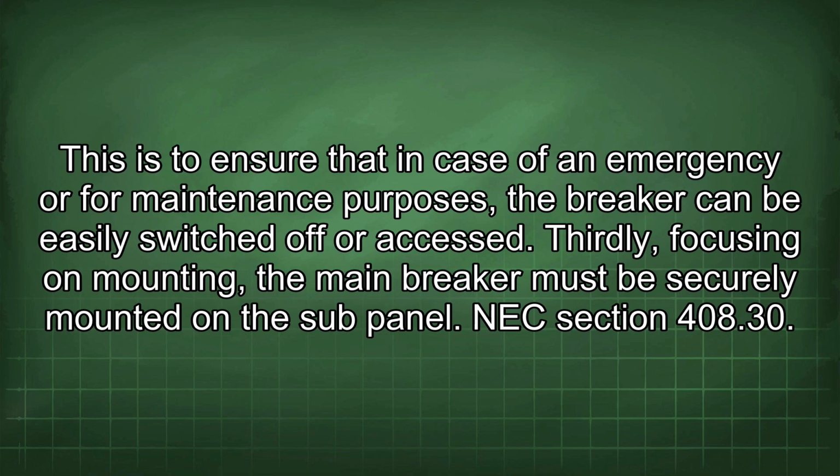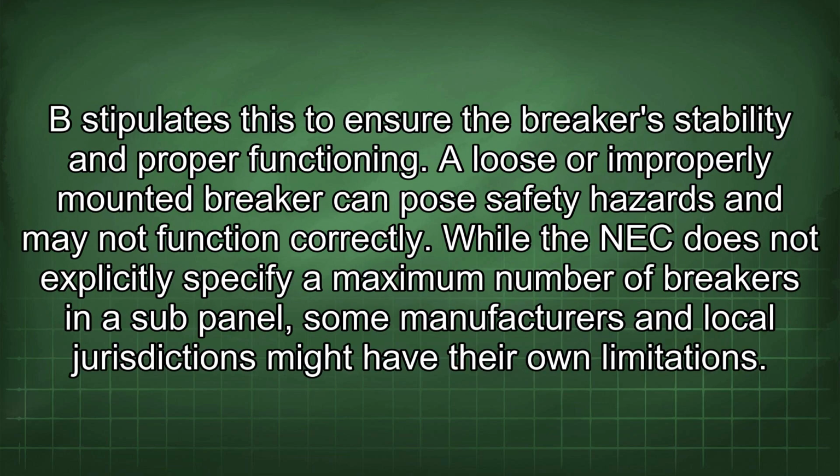Thirdly, focusing on mounting, the main breaker must be securely mounted on the sub-panel. NEC section 408.30 B stipulates this to ensure the breaker's stability and proper functioning. A loose or improperly mounted breaker can pose safety hazards and may not function correctly.